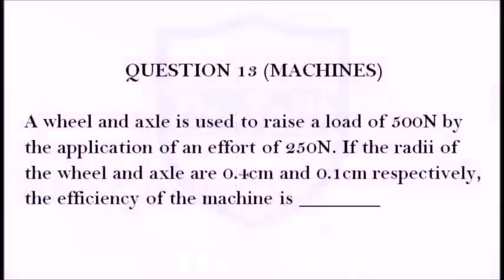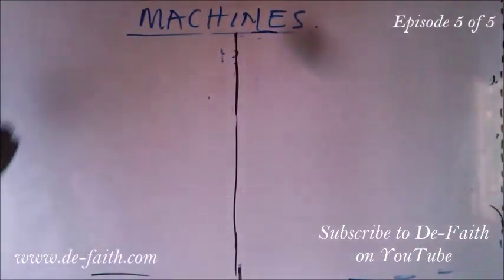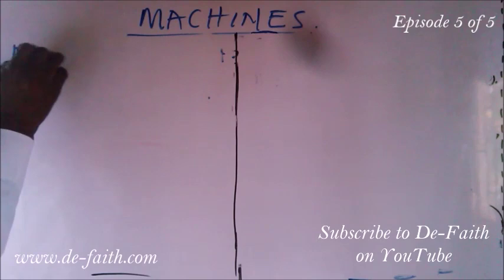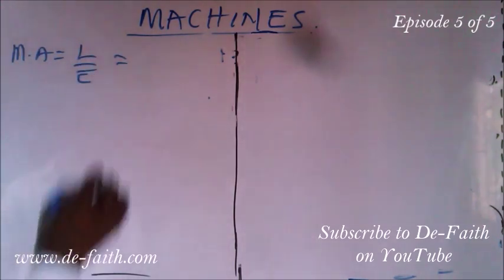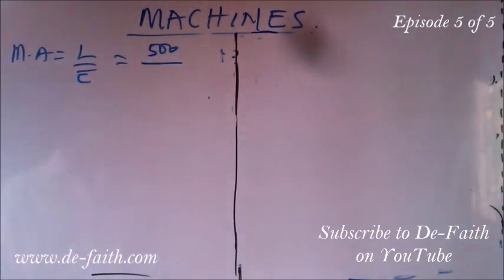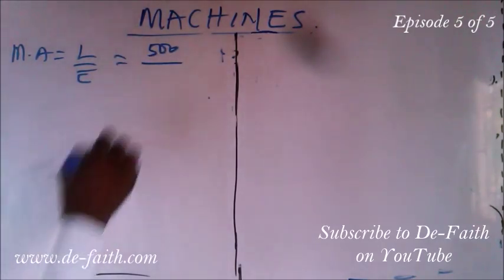This next question says that a wheel and axle is used to raise a load of 500 Newton by the application of an effort of 250 Newton. If the radii of the wheel and axle are 0.4 cm and 0.1 cm respectively, the efficiency of the machine is what? This question is quite straightforward in that we can calculate our mechanical advantage by saying load over effort. The load given here is 500 Newton and the effort given here is 250 Newton.